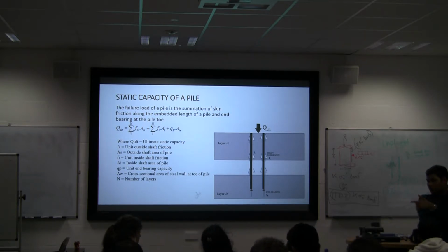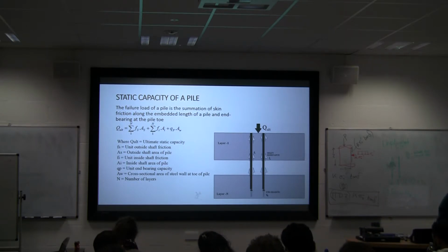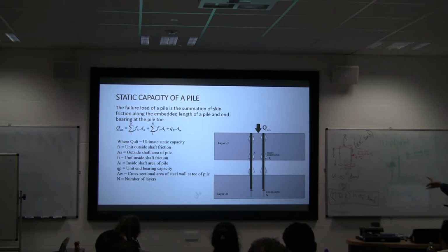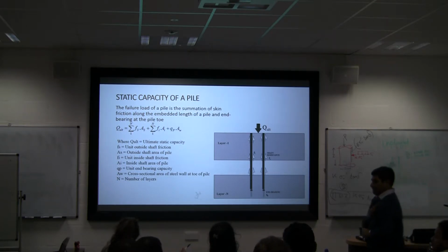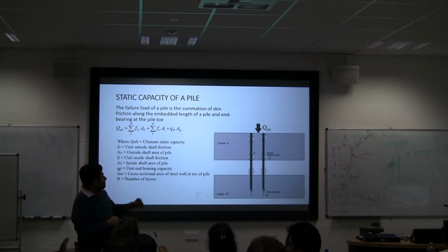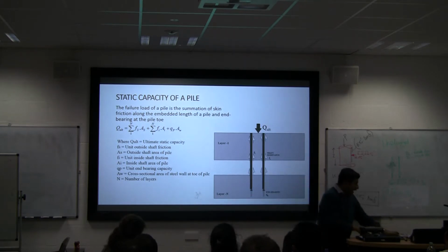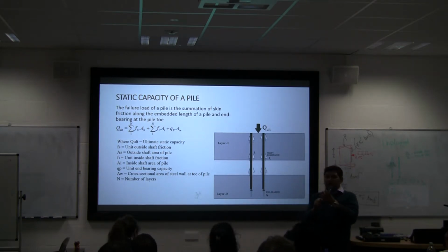Now what I will show you is, if you use this code that I gave you, an API code, they are all different. What I have shown you is the theory. So you can see how the code interprets that and gives the guidance. Here we are taking the effective stress in the middle of the 1 meter. So that's the pile, right?